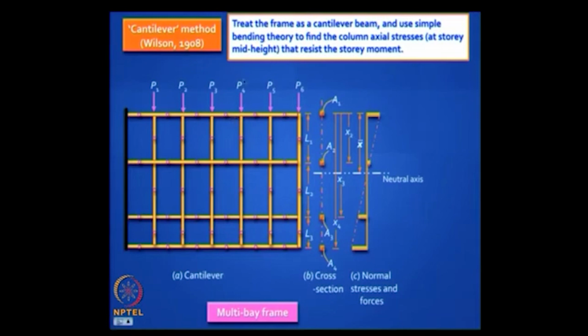Well, according to this theory, we treat it as a linear variation, assuming simple bending theory. It is like a truss, for example. Is it clear? But you have your beam has solid quantities here, here, here and here, and this is your stress distribution. Is it clear? Now it is obvious that you will have compression. Where will you have compression? At the bottom and tension at the top, and you have a neutral axis and so on.